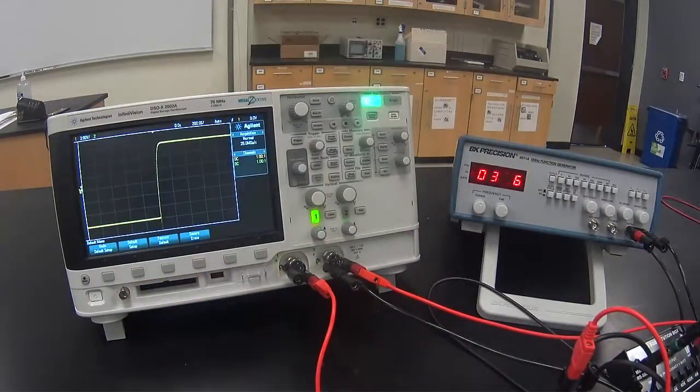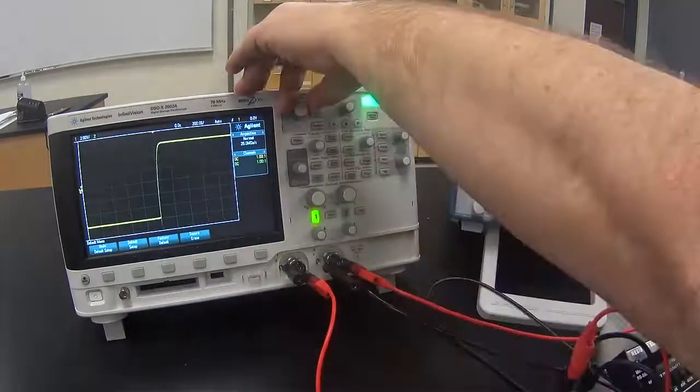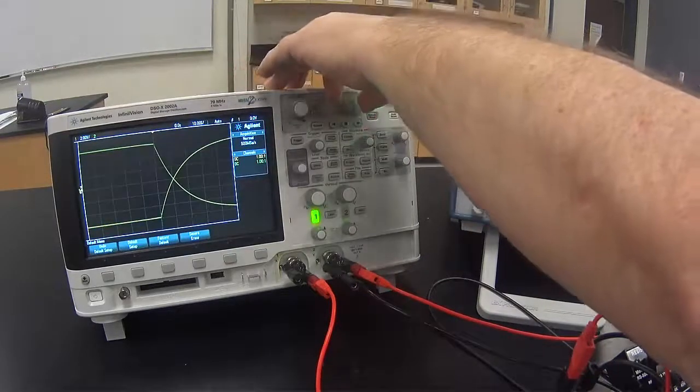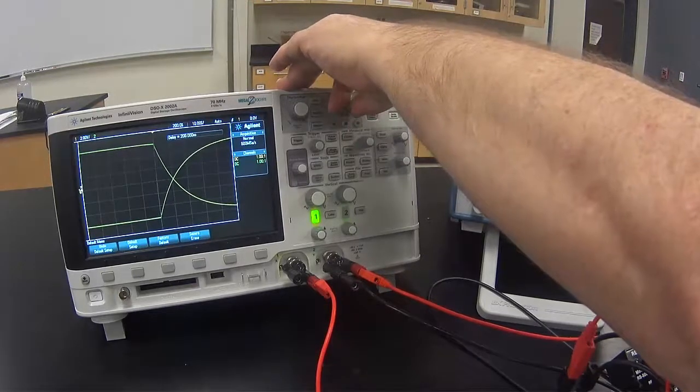If I were to try to measure the time it takes to go up 3 divisions on this time setting, it happens in such a small amount of time compared to the time setting that I could not measure it accurately. So I'm going to stretch out my signal by changing the time setting. Notice that I have 2 parts of the curve here. It's a triggering issue and you may not be able to solve it.